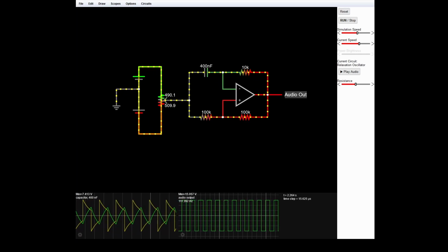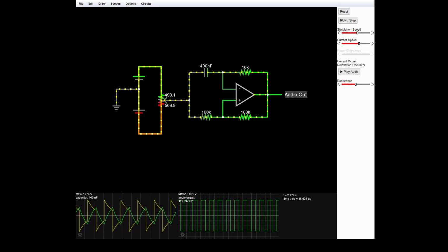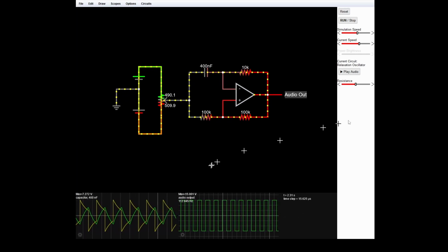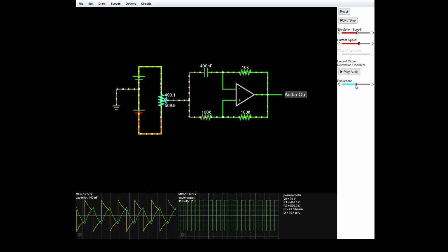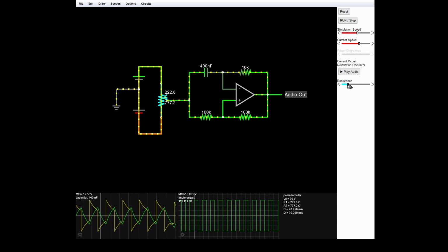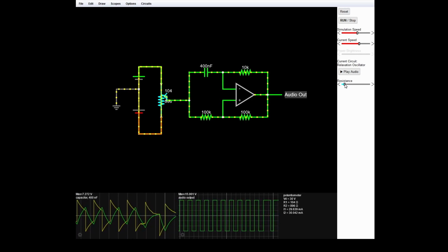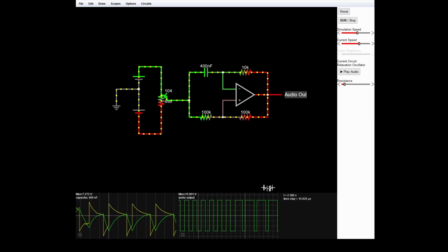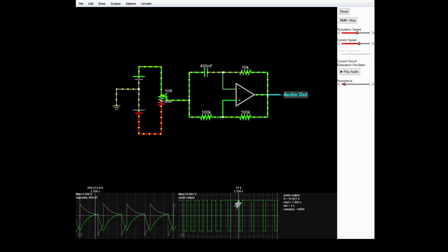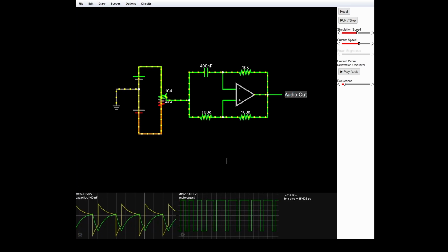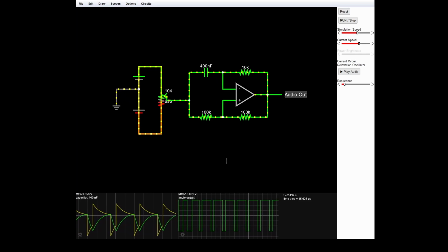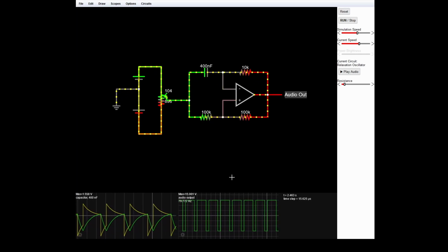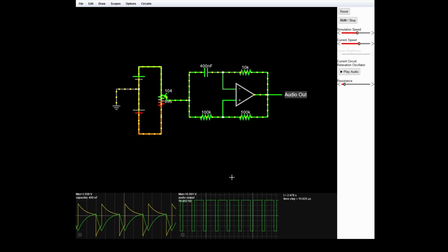Yeah, it's 111 hertz, so it went down to 83 hertz. Now I'm predicting that if I move this up to lengthen the duty cycle, it's going to drop the frequency the same amount. So let's move it over. Put that about 104 ohms on top over 800 ohms. And notice over here, definitely we did lengthen the duty cycle. So it's at high voltage longer than it's at lower voltage. And it's still calculating. There we go, 79 hertz. So exactly what I predicted.